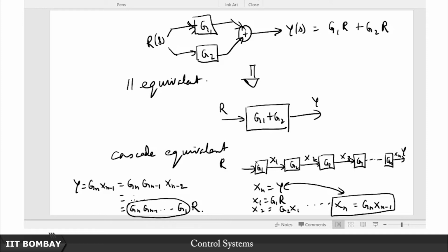So again I might warn you that when you are dealing with SISO systems here, it really does not matter in what order you multiply, but the way I have shown you here, this is actually applicable for a multivariable system as well, right, where of course these could be multiple inputs, multiple signals flowing in between these blocks, alright. So therefore this order will be of significance when you are dealing with multi-input, multi-output systems, okay.